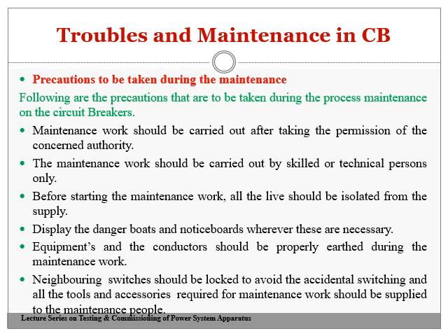Before starting the maintenance work, all live conductors should be isolated from the supply. That is, all live conductors supplying the particular circuit breaker under maintenance should be removed. Display the danger boards and notice boards wherever necessary.